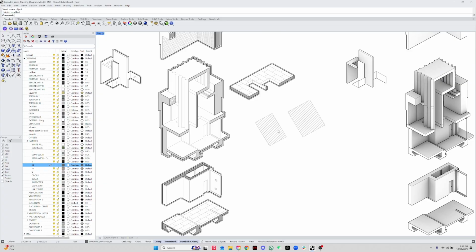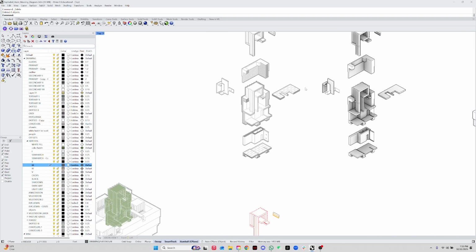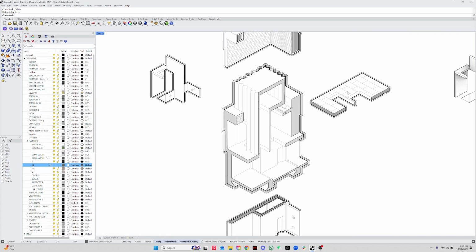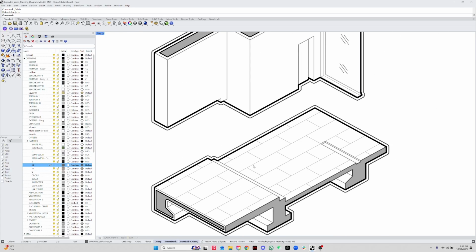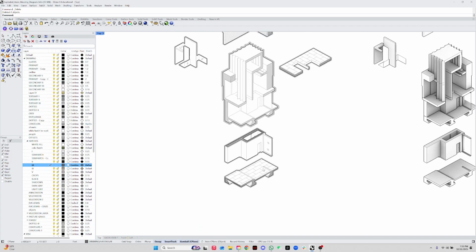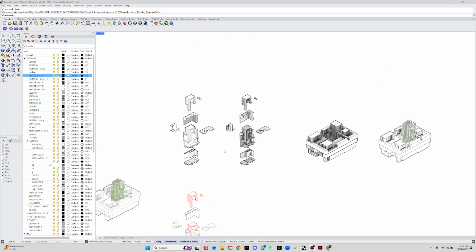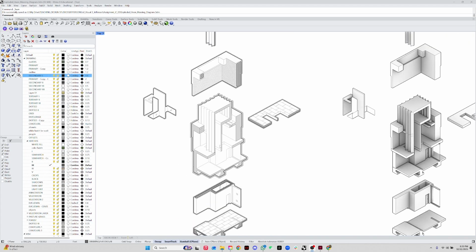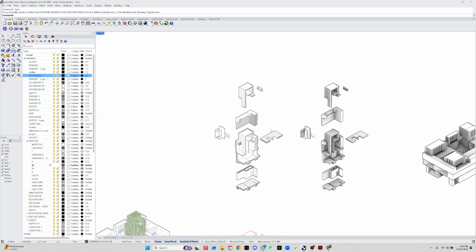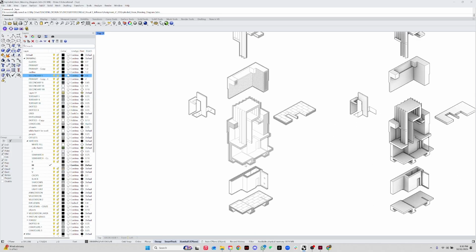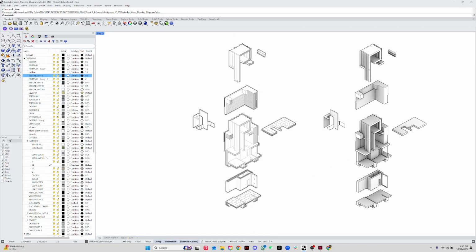So this is super useful once you're going from the model and you're extracting the surface, putting it here, and then going back and forth. It helps a lot to match properties, so then you don't have to go look for the hatch and do it again. Okay, now that we have the drawing done, now we can print it. So we can either print it as a PNG or we can print it as a PDF. For this one specifically, we're gonna do it as a PDF.